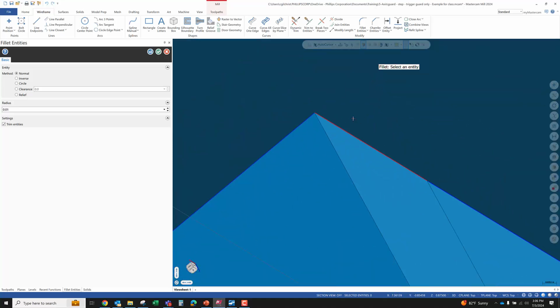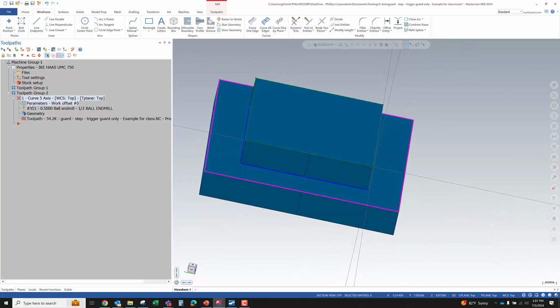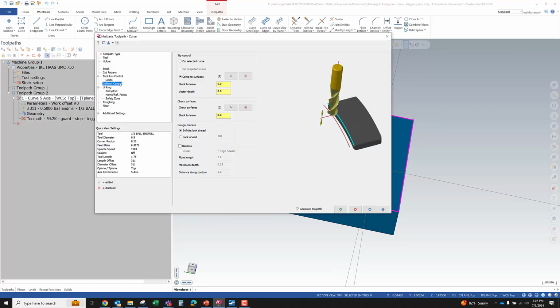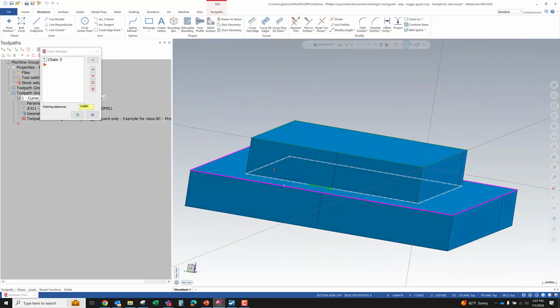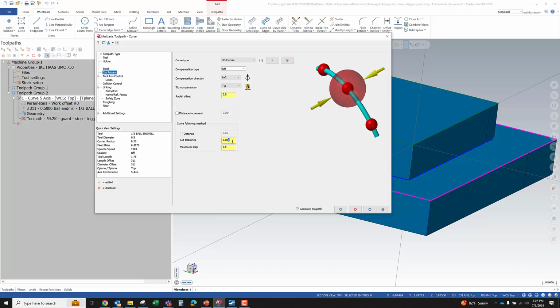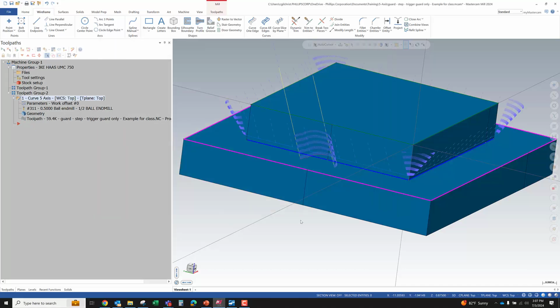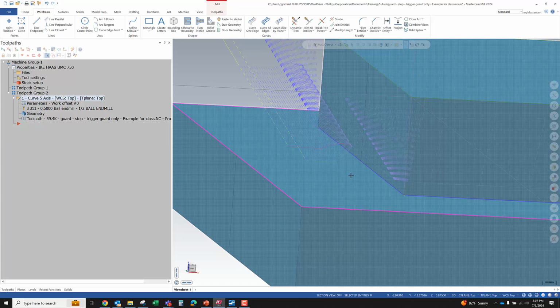It's going around these corners. Now that should have kept our chaining association. Yep. So adding a trim will automatically add it to that chain, so we should be good there. And we probably want to increase this to more like 1/10 instead of 1/1000. We've still got a 1/2 inch maximum step. Better. Gave us something to figure out the transition on.